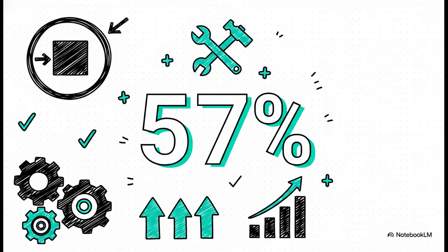And honestly, if you take nothing else away, look at this number, 57%. Moving to GD&T's circular true position tolerance zone gives a machinist exactly 57% more workable area than a traditional square zone. I mean, out on the shop floor, that translates to a massive reduction in scrap. You're giving them a bigger target to hit, which directly boosts the bottom line, simply by correcting the shape of the tolerance zone.